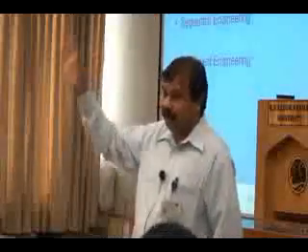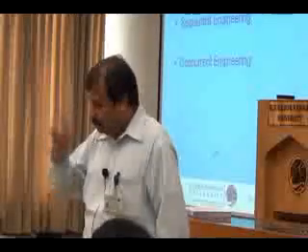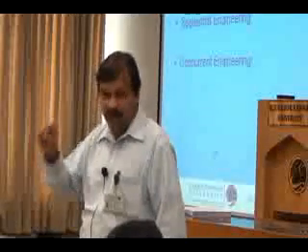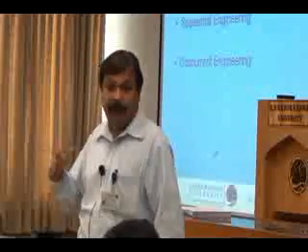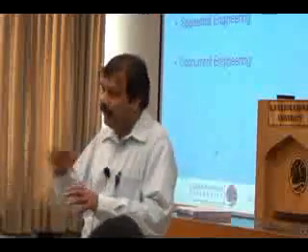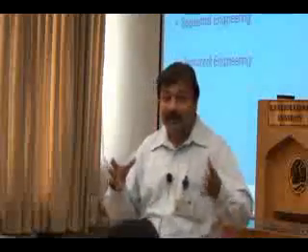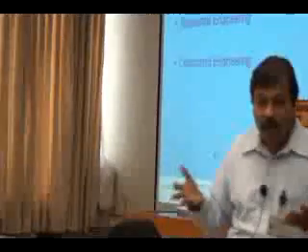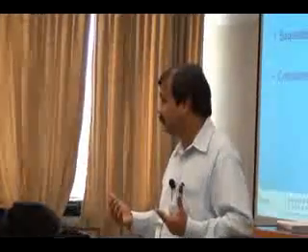First, you have to understand the need, the voice of the customer. Then you have to list down the specifications: this is what I want my car to do. Then I have to develop some concepts to realize these requirements, evaluate the various concepts, and model it, checking whether this concept will really work. Then I go for a detailed design, meaning arrive at the drawing of each and every part.